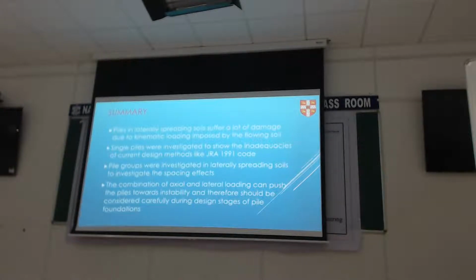And they suffer even more if you have this non-liquefiable crust on the top, because compared to the liquefied soil applying a lateral force on the pile, the non-liquefiable soil can apply a lot bigger forces. Now we've shown this J record is complete, but inadequate for sure by a factor of 2.5 for single piles. But again, as I said, they have upgraded their code to be fair.